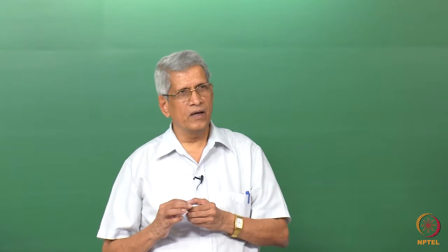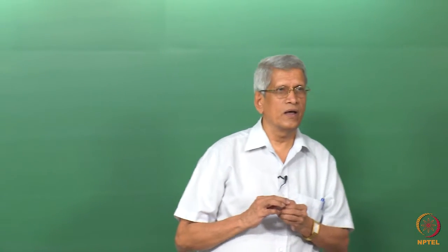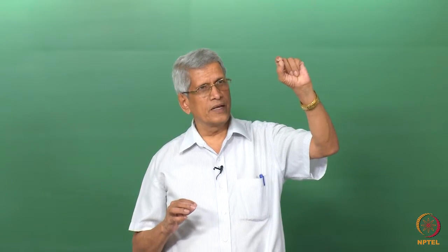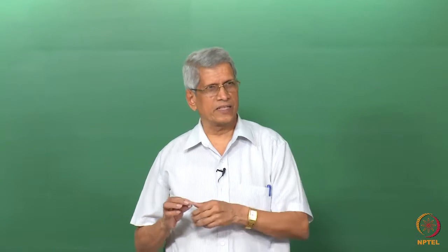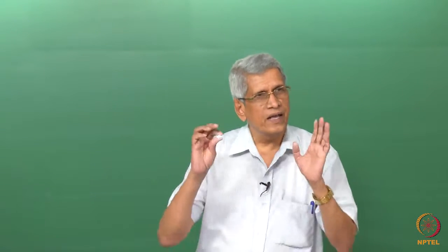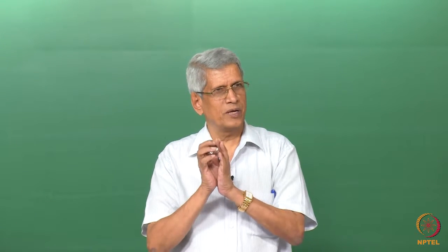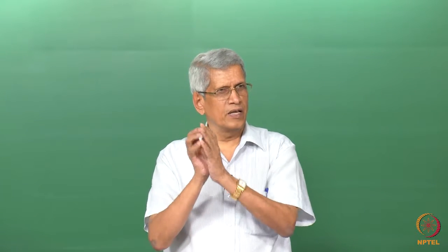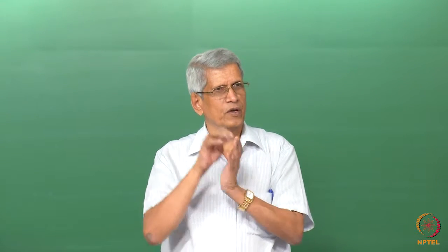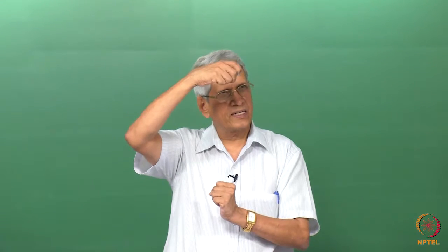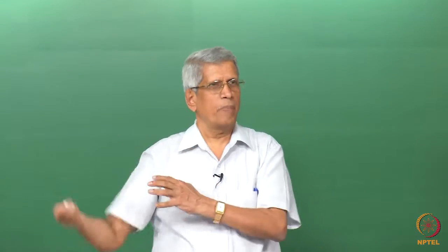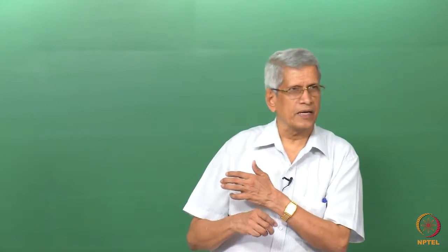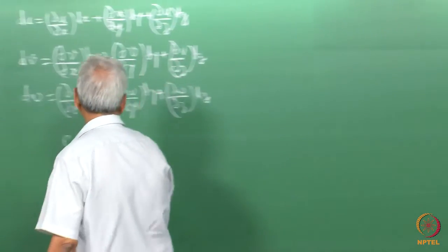Yes, sir, but u still, the length scale is still along x. Del u by del y. Yeah, du when you consider is essentially a displacement of x in the x direction, okay. V is the displacement in the y direction. W is the displacement in the Z direction. But that will have a contribution from strain which is taking place in that direction, plus some part of a strain which is also contributing, that could be a shear strain, that direction. Okay. So that is what we essentially write it as.